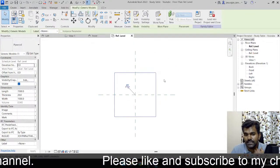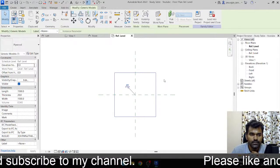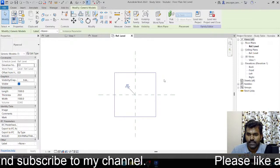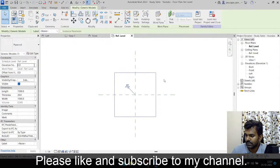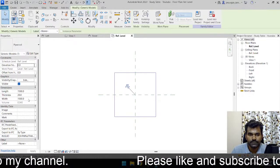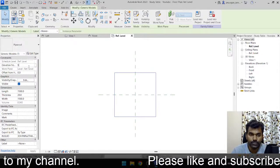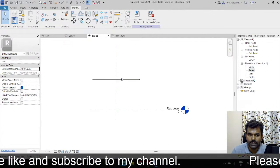Now decide your table height. To decide your table height, you should think like an architect, right? In case you stand, what's the height to your hip? I think that's the height. So I'm just going to keep it as 900. Select the plywood and then check the offset to 900. Go to front. So this is the height.